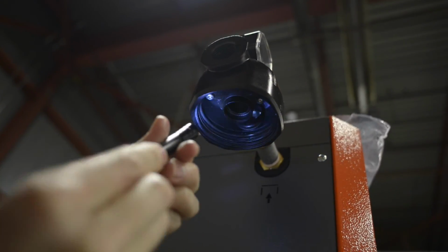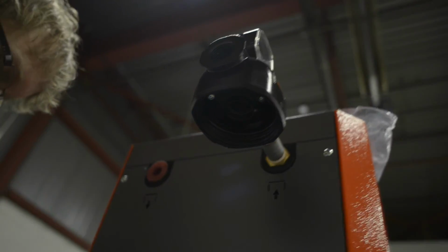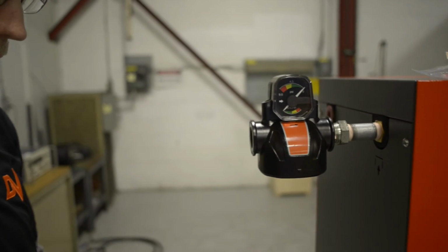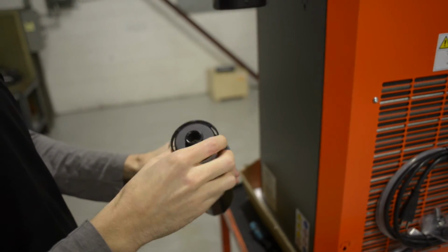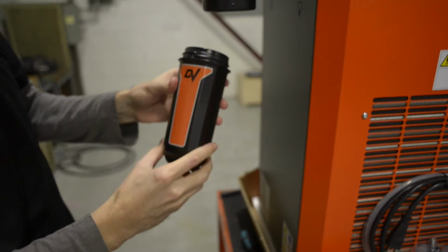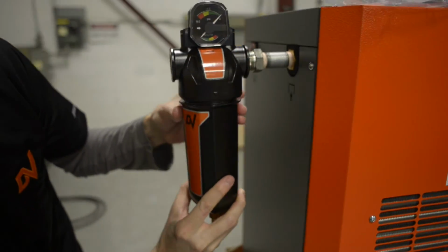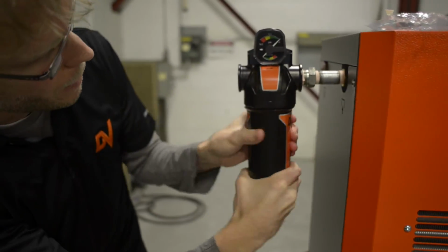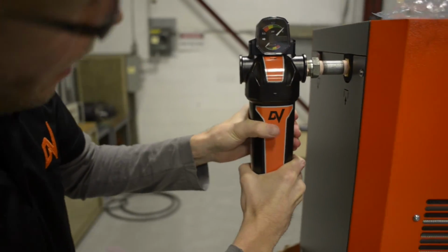And we'll just double check to make sure it's seated correctly and looks good. So we will now put in the filter. The filters are self-centering. You simply put it in the filter body and you see it's centering. You don't have to screw it onto the top. You just simply put in the canister and then twist the canister back onto the head.